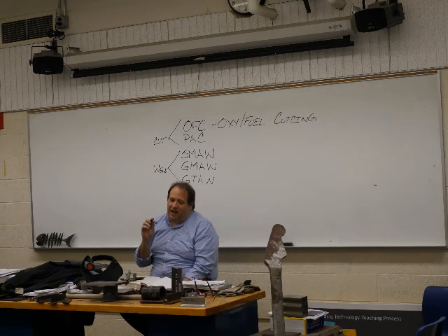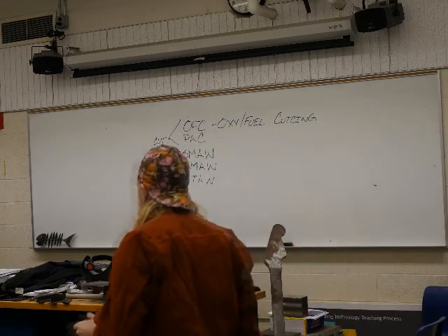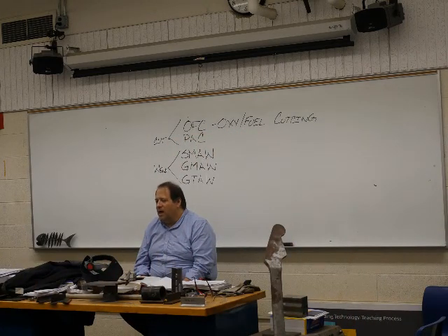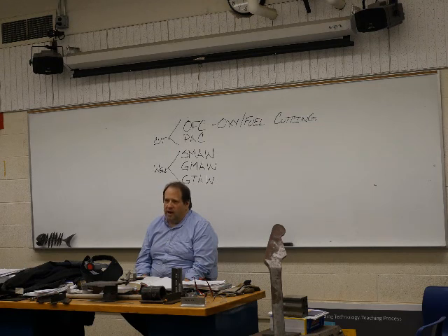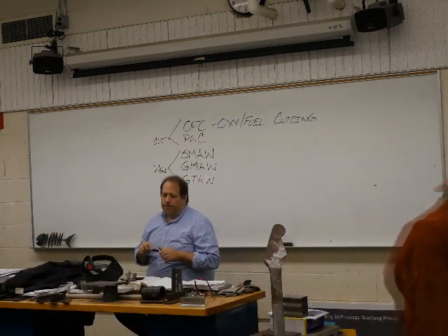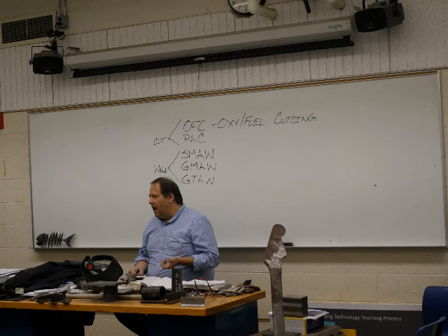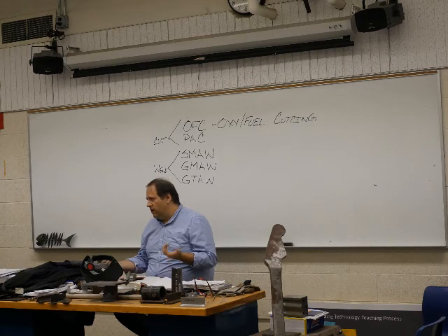So acetylene is a pretty volatile gas. It's been used forever and ever. But it's a pretty volatile gas, and it's very expensive. And there's all kinds of little issues with acetylene, but it still works really well. Our main thing is that it's not very cheap. So we've switched it over because propane actually works just fine for cutting, where acetylene will really shine for the welding side of things. So we are using this propane gas. There's other gases. There's nat gas. You can use natural gas. You can use a hydrogen gas. You can use all kinds of stuff that will light up.